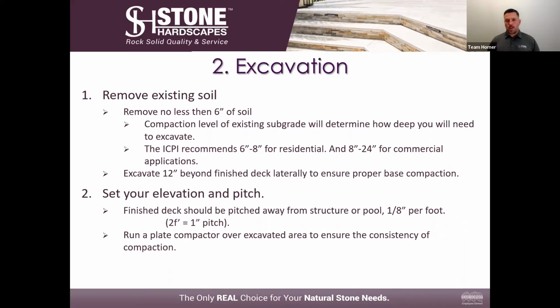What you do not want to happen is to put a deck around a swimming pool or a deck next to a house and have the water run back to the house. Typical concrete is 1/4 of an inch. Segmental decking is 1/8 of an inch. Keep that in mind when you're talking to somebody or you're doing the installation yourself. It is a very important aspect of making sure that your elevation is correct and your pitch is correct away from the structure.